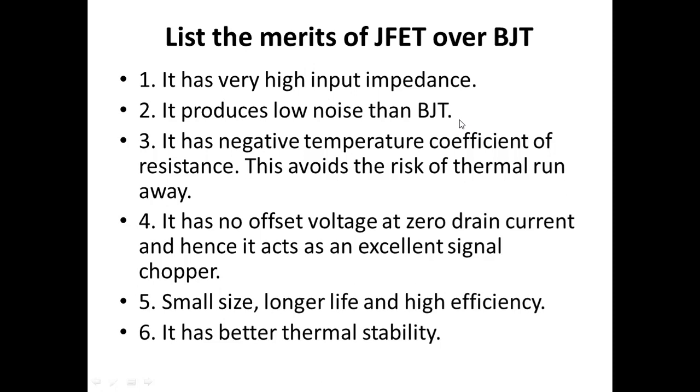It is a continuous and cumulative process in which the BJT, the normal transistor, may burn out. That is known as thermal runaway. In this case, the field effect transistor has a negative temperature coefficient. That means if the temperature increases, its resistance value decreases. Hence, it avoids the risk of thermal runaway.